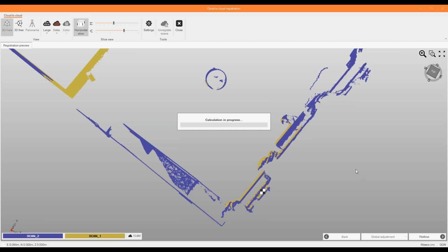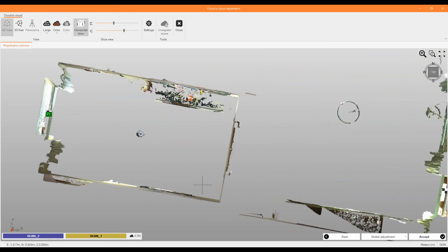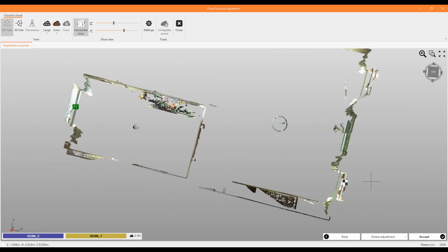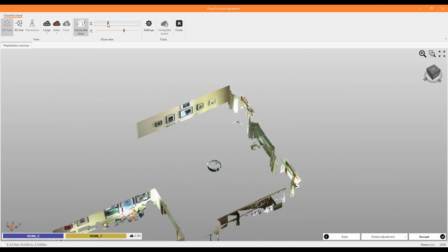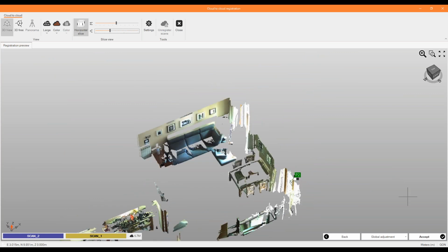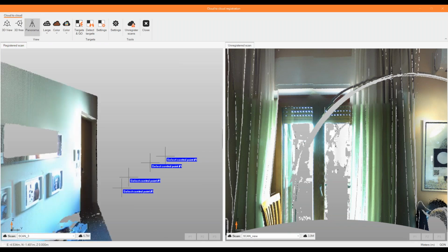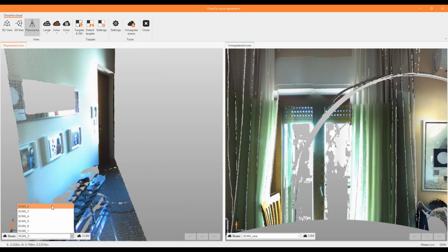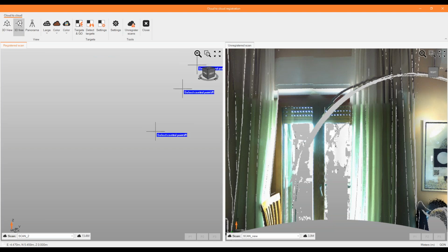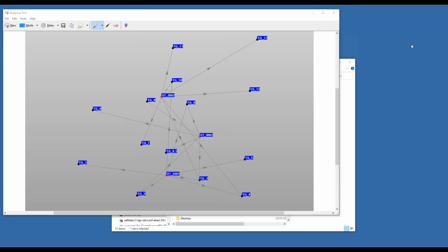and here we can simply orient the scan number 1 on the scan number 2. 5mm error, just because we did it very quickly. So the error here is reduced. I can accept it. Now again, the software will move to the next scan, which is not registered. You can also move and select another reference point cloud, or we can use the other registration.